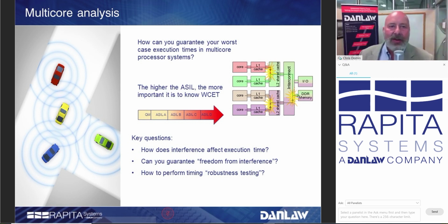Multi-core processors handle multiple functions and simultaneously compete with each other across those resources from each core. This effectively means that the algorithms on each core will interfere with each other and further increase the worst case execution times. And the impacts of this can't be underestimated.